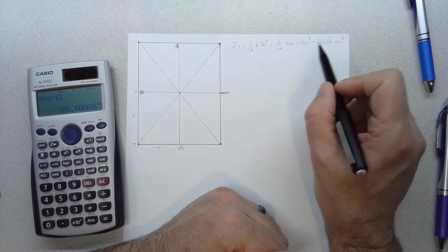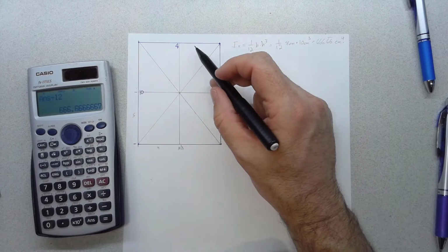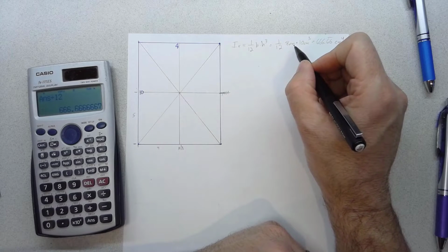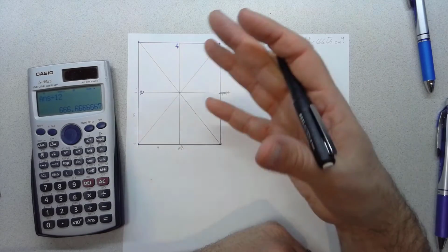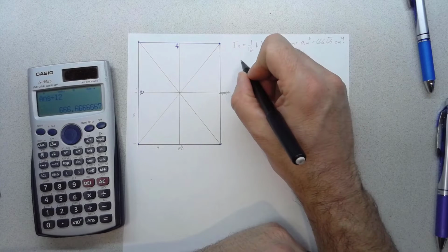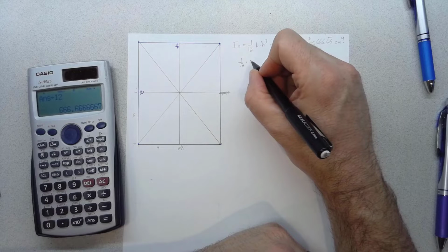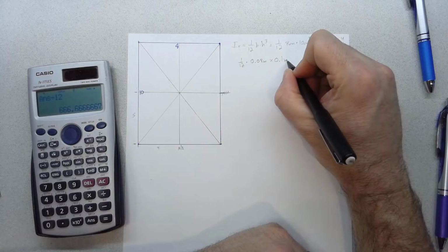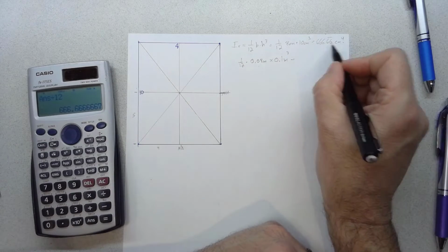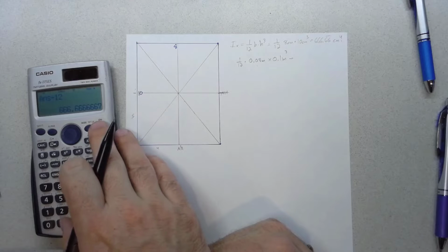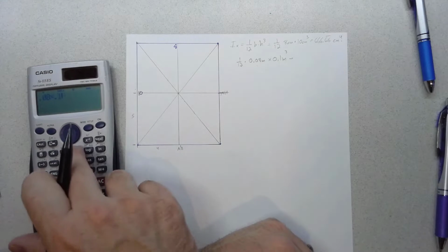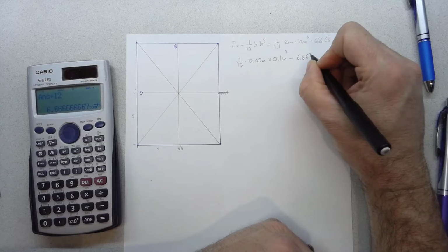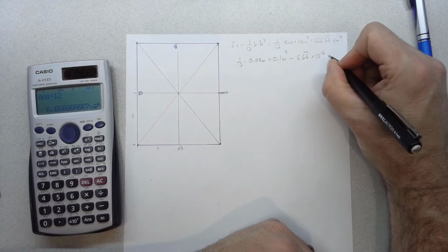Key idea also to keep in mind: I did it in centimeters here because that's the units I used when I was drawing it out, but in reality, if I were doing this for an engineering problem that I was actually going to solve, it might make better sense to do it in terms of meters so that when we plug in newtons for our force, etc., all our units work out correctly. So in that case, I would write it out as 1/12 base 8 centimeters is equal to 0.08 meters times 10 centimeters, that's 0.1 meters cubed. And so that should end up with the same number, 666, etc., but it's going to be a different power, definitely. So 0.08 times 0.1 cubed divided by 12, and that comes out to 6.66 repeating times 10 to the negative 6 meters to the fourth.